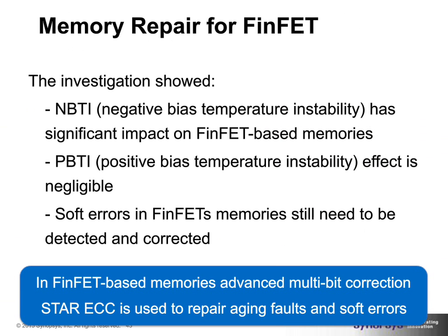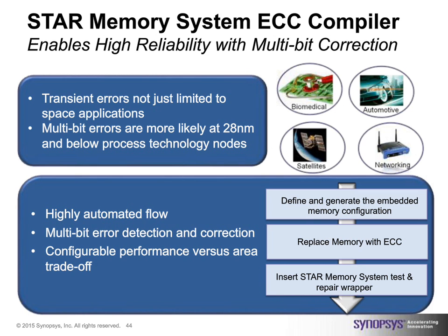So we have developed a solution on the STAR Memory System called STAR ECC. This will allow us not only to do classical ECC, which is multi-bit detection and single-bit correction, but multi-bit correction as well. FinFET solutions would require these as long as reliability is important for that chip and lifelong health is critical. So repairing periodically, being able to take care of aging and soft error problems, whether periodically or online, are part of the FinFET solution.